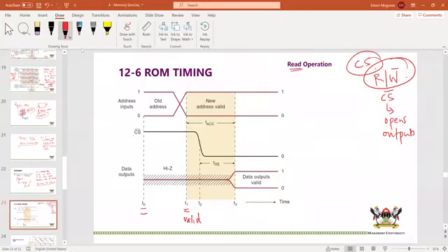You can see the chip select was in the disable state, and now after the addresses have stabilized, it comes into the enable state, it goes 0. Now during this whole time, this dashed line is the high Z, but when the chip select goes low, there is a certain time duration before the memory actually responds to the chip select. But once it responds, the information in the provided address will come to the output.